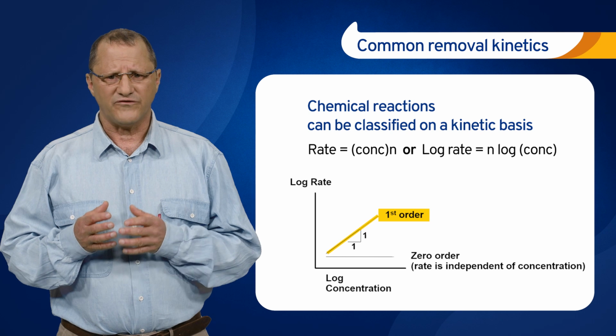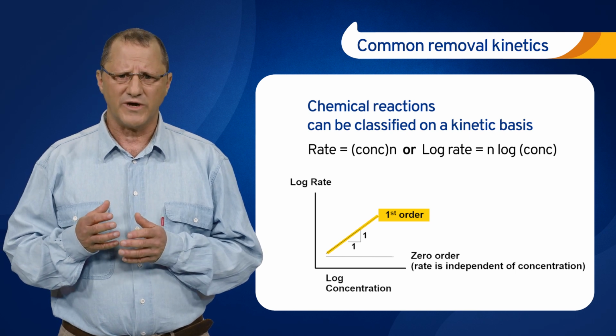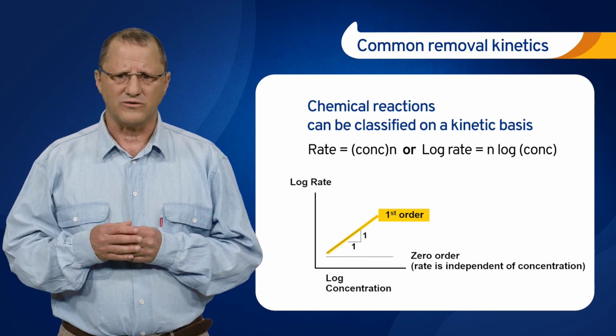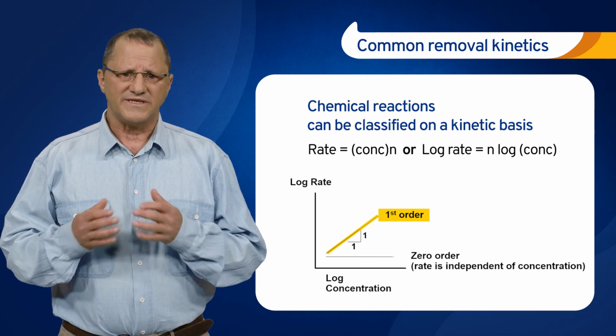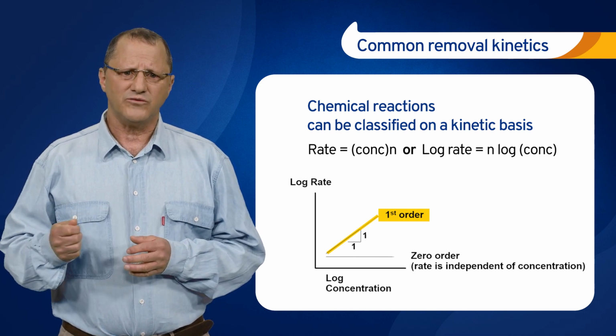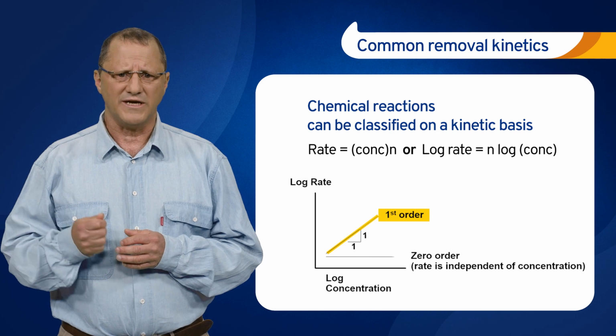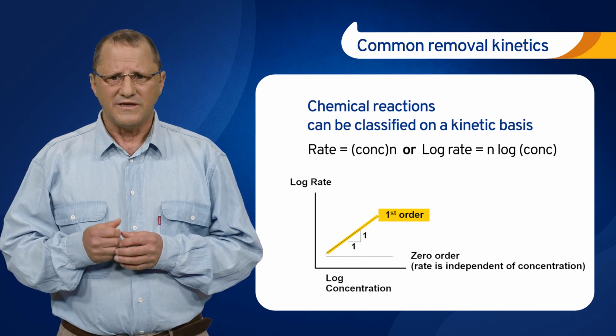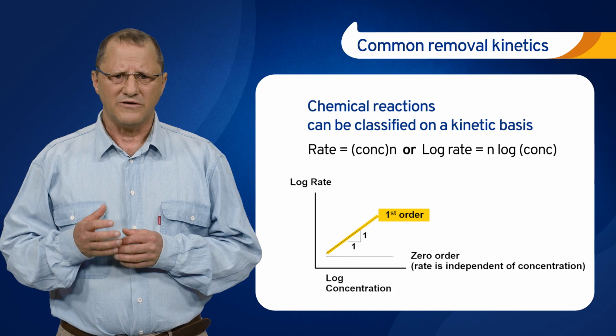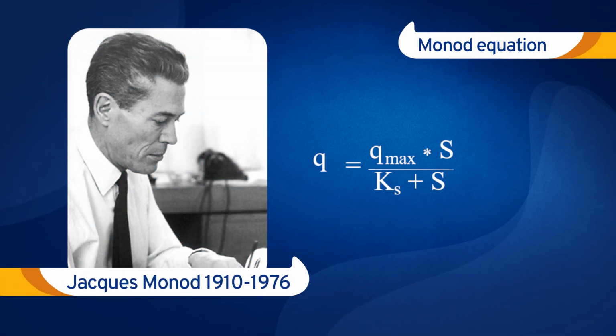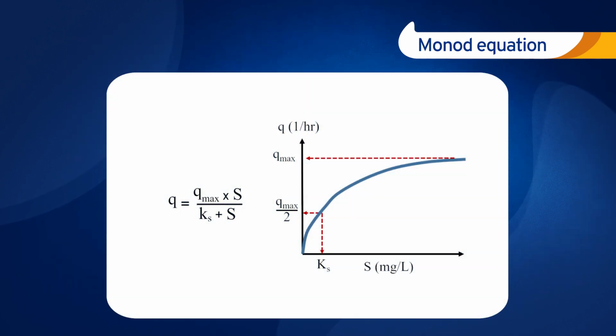First-order kinetics refers to an increasing degradation rate as a function of substrate concentration. Or, as in our example, the degradation rate increases with increasing organic matter concentration. This kinetics is more typical for lower concentrations. The empirical Monod equation for substrate degradation, or in our case, organic matter degradation, describes this concept well. It can also be seen graphically and will be further explained.